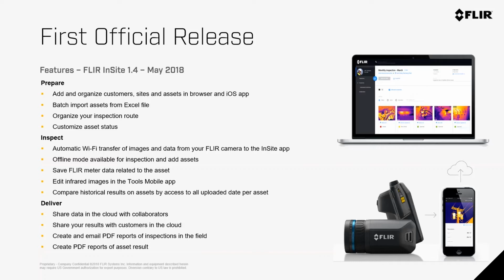You're going to be able to enter site locations, enter these surveys, and enter assets while you're in the field. While you're in that inspection phase of FLIR InSite, you're going to be able to automatically Wi-Fi transfer those images. It's going to automatically know the last image you took on your camera, and it's going to pull that into FLIR InSite just by the click of a button.